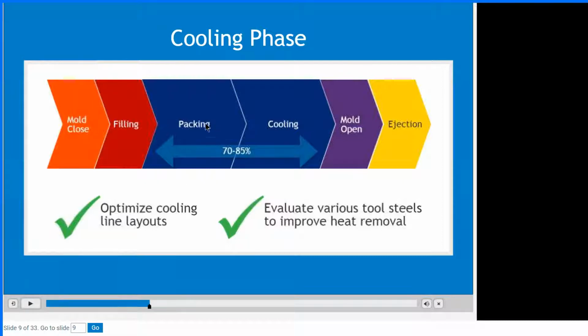Now, why did I put packing as part of the thermal phase? Well, remember in the molding cycle, when the material is heated in the machine barrel, it's hot, it's injected through the nozzle and nozzle tip into the mold, and as soon as the material hits the mold steel, the cooling phase begins. So part of the filling phase is already cooling the material, but mainly when we talk about the cooling phase, we mean the packing phase and the cooling phase, or what we also call remaining cooling time. So packing time and remaining cooling time is the cooling phase.